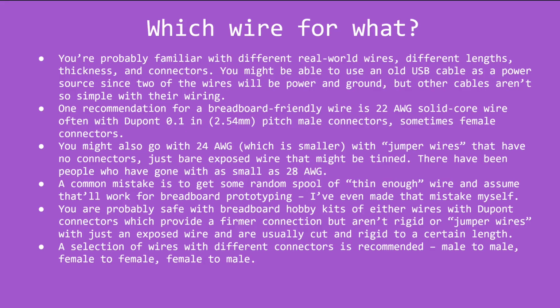A very common mistake for hobbyists is to just find a wire that's just thin enough to fit into a breadboard and assume it'll all just work. I've even made that mistake myself. Your best and safest option is just to buy packs of wires for a breadboard in one of the two configurations I mentioned, actually probably both, and try to cover all your bases, so male to male, female to female, male to female.